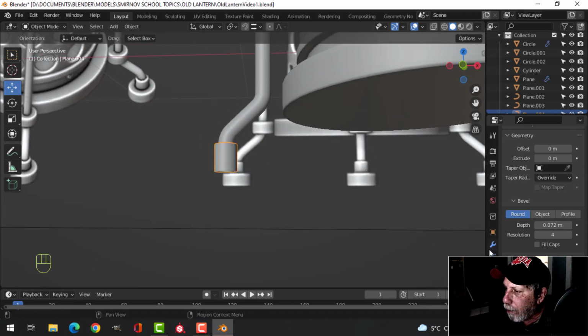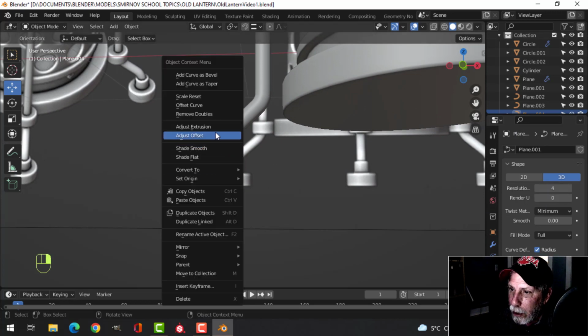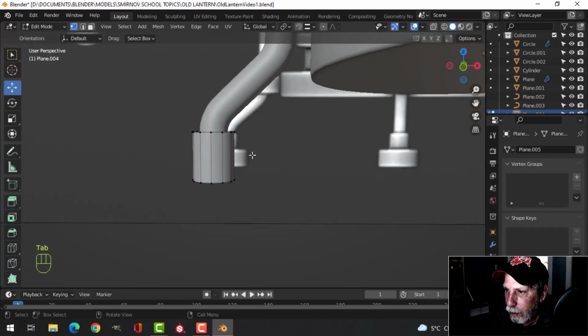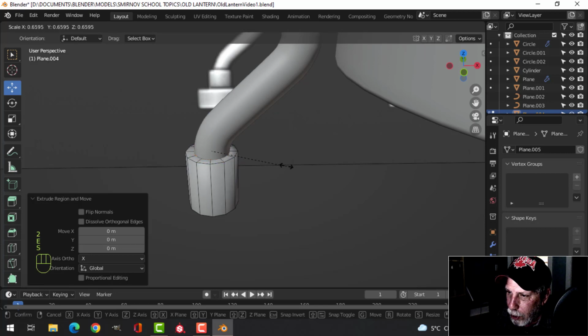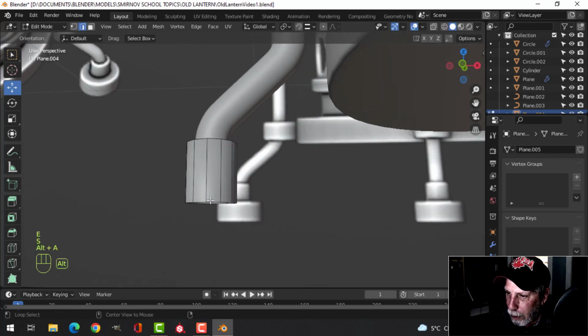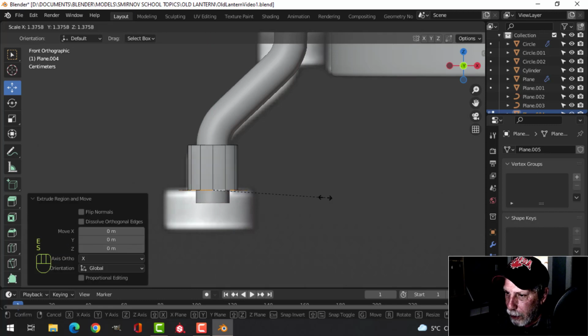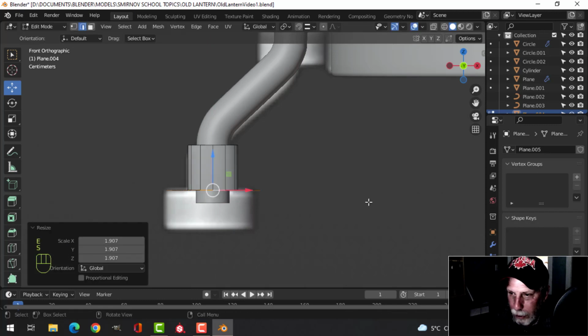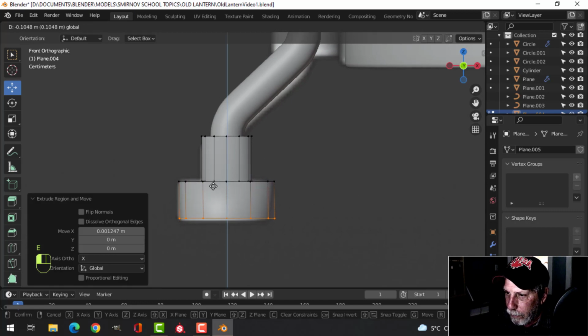We'll convert that to a mesh. So come up here, change your resolution first to about 4, so that when you convert it to a mesh, it's not too dense. So we have that, that's fine. Select this top, E and S, just pull it in. Select the bottom, let's look again. I'll come up here, E and S, I'll come out. Again, I like to see the vertices, E, and come down. I may have moved it a little bit when I do that.